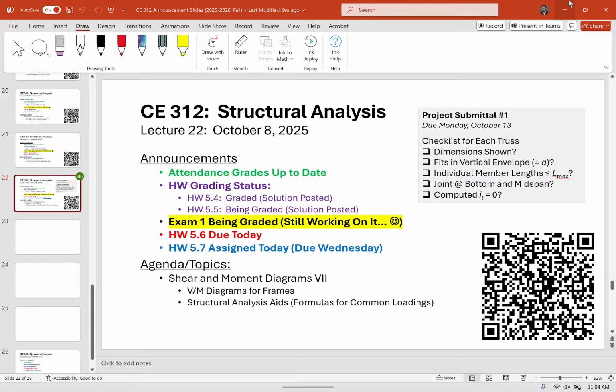I mentioned, I think, in my suggestions for your truss that depth equals stiffness. The deeper the truss is, the stiffer it is. So if you have a really, really shallow truss, you're probably using some really, really big elements. If you have a truss that's 5 foot tall, 6 foot tall, you're going to use really big W12s on that. Whereas if you have a truss that's 12, 13, 14, 15 feet tall, the W12s are going to be a lot smaller. So it's not no, it's just that might happen.